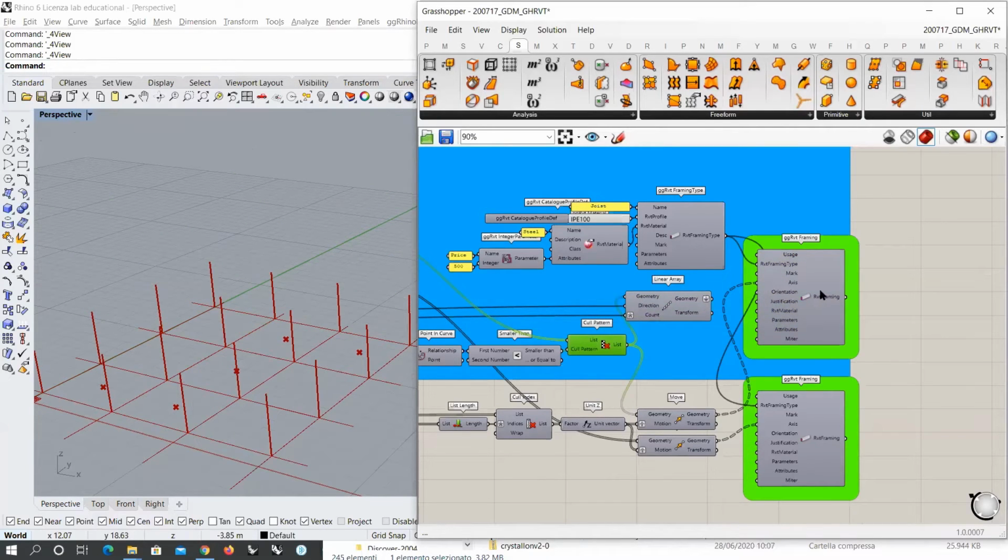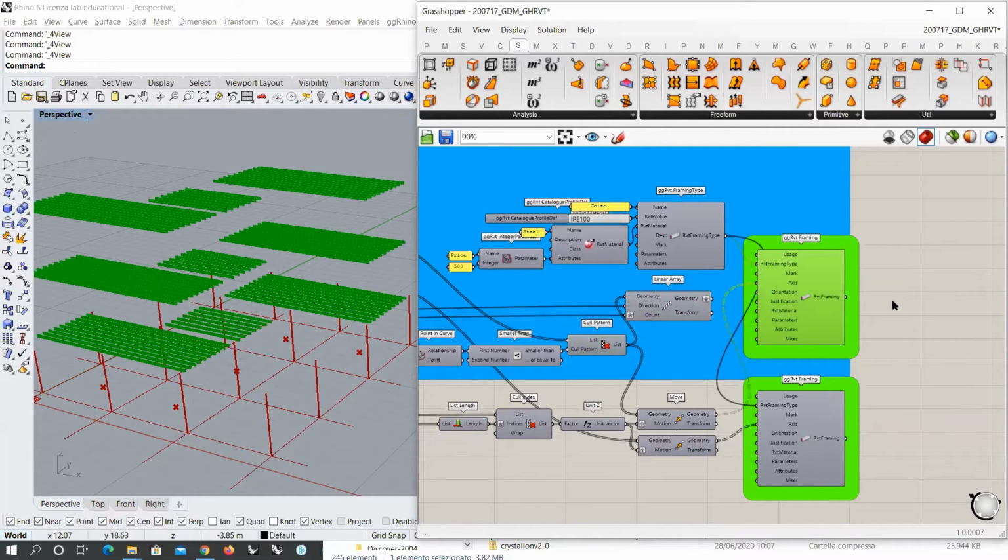Okay, there is a reason for this, and this is actually something that I was also observing in the Rhino to Revit export process via IFC. For some strange reason, the linear array is not always working properly. So I think it depends on the way that object ID is defined using the linear array. I found out that if you copy things instead of using a linear array, for some types of elements, it worked better than the linear array.